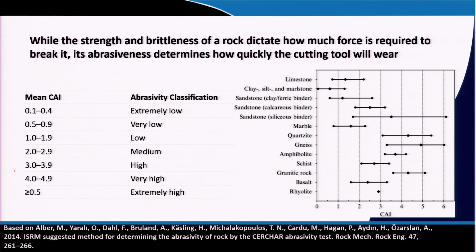Then you cannot use just iron or steel directly; you will have to go for some alloy steel, or sometimes you will have to do surfacing, that is brazing or hard facing, so the manufacturing process of the tool will be different.